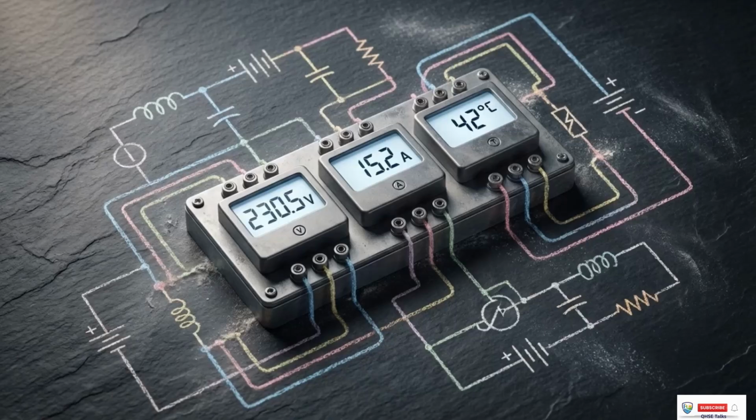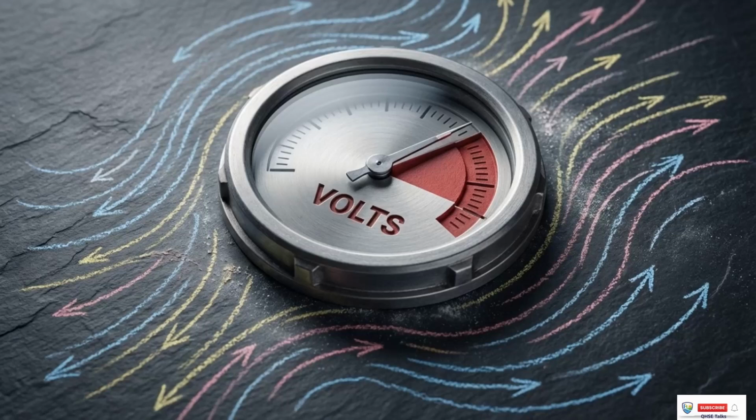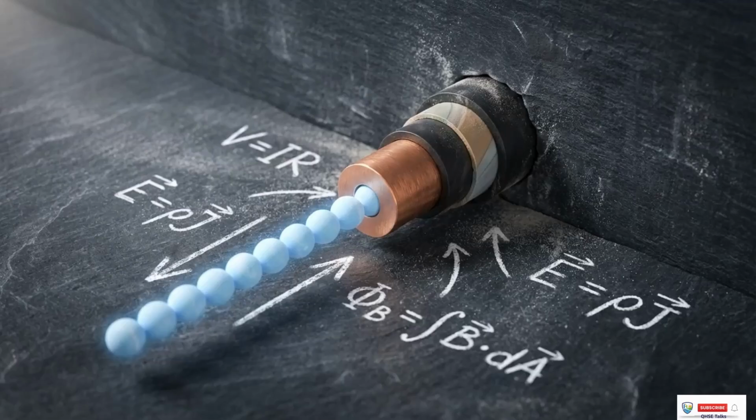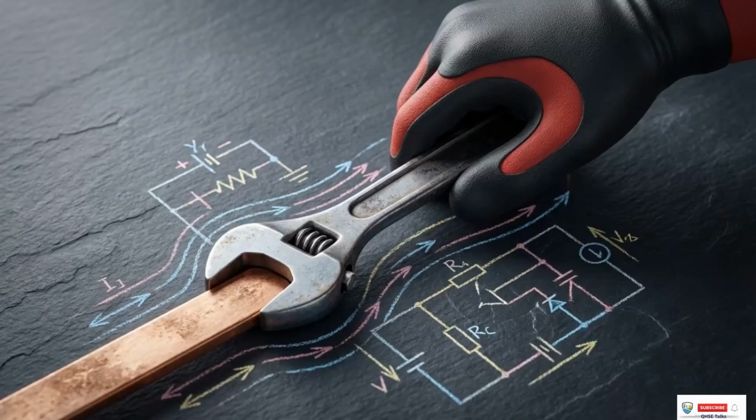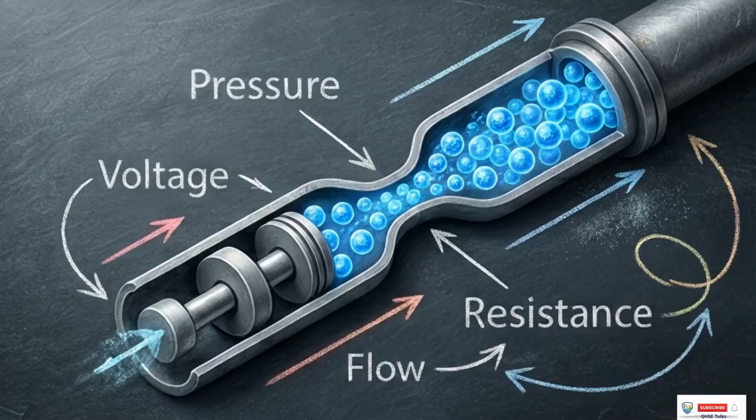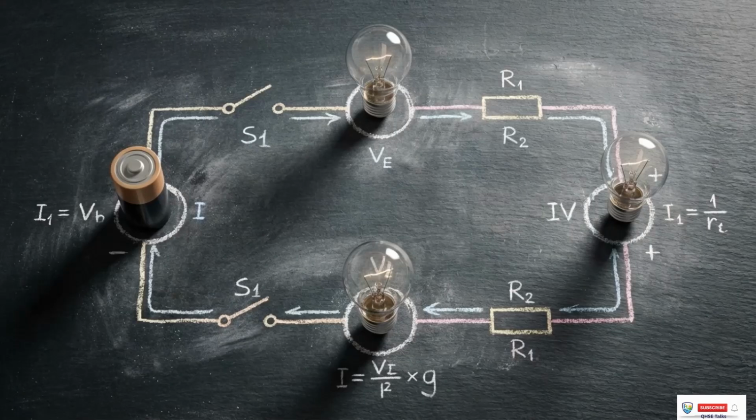Electricity is governed by three primary variables. The first is voltage, measured in volts. Voltage is the potential difference, or the electrical pressure that drives a system. The second is current, measured in amperes. This is the actual flow rate of the electricity. In human exposure, current is the specific factor that determines the severity and lethality of a shock. This model demonstrates their relationship. Voltage acts as the pressure pushing the current, while the third variable, resistance, measured in ohms, acts as the physical restriction opposing that flow.